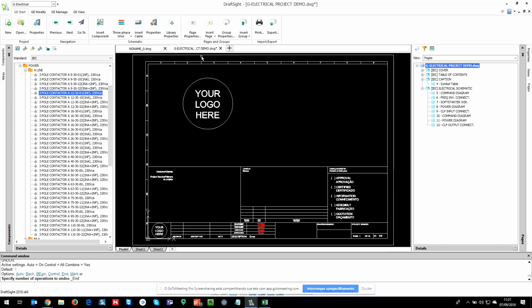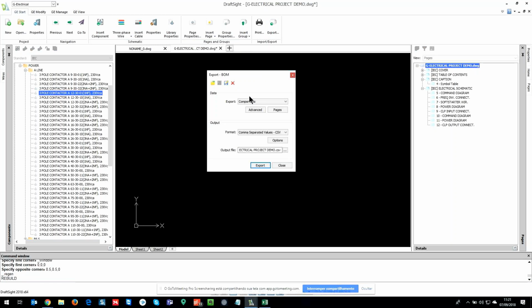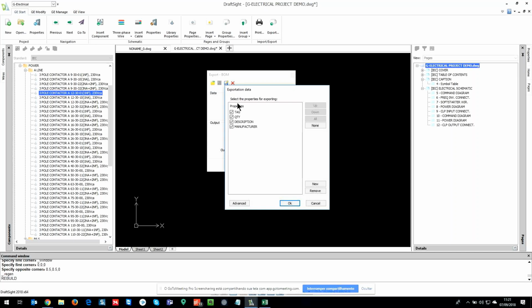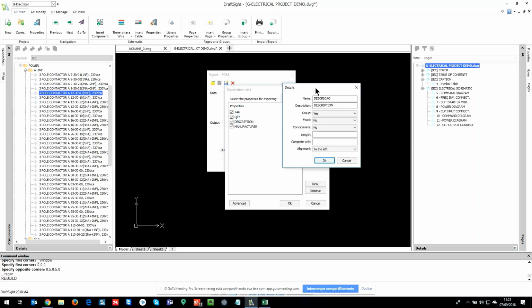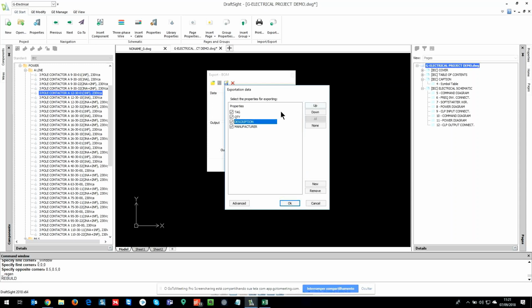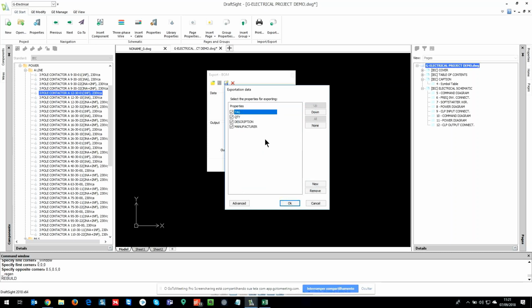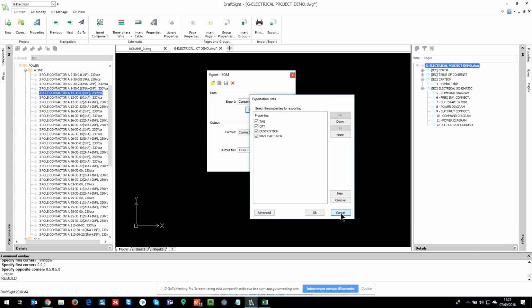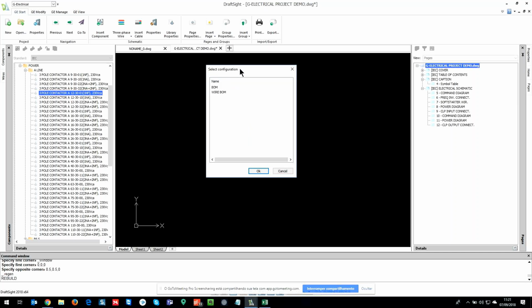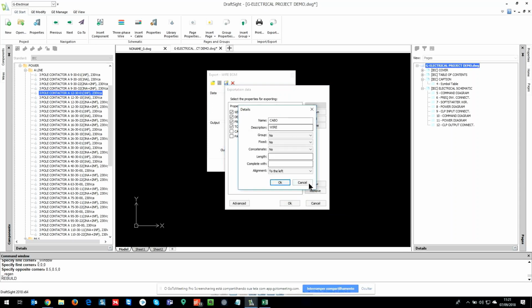The customization of our lists is very easy because we simply have to work with the attributes which bring the information we need. We have some standard attributes, for instance, the description of our components. Once we have this information added, we can store it in a normal standard report like the wire BOM. So we have the wire information, the description of the wire, and the from-to information.